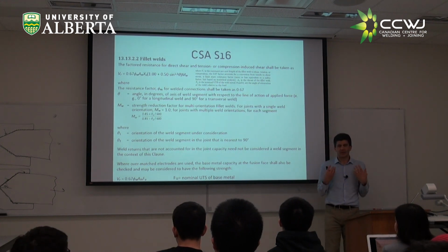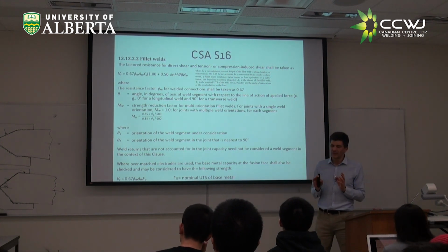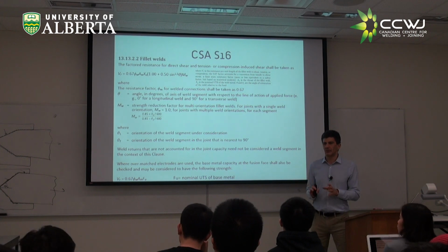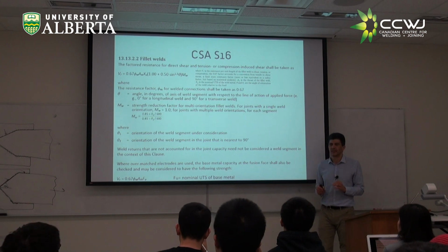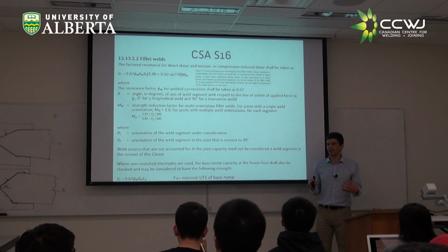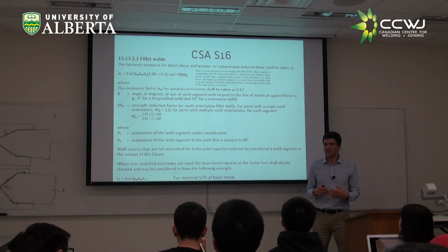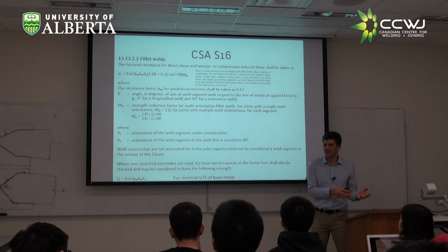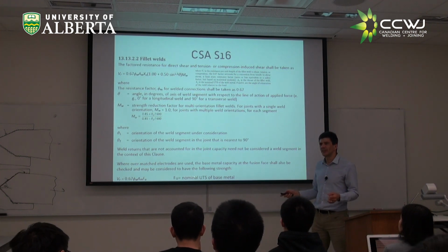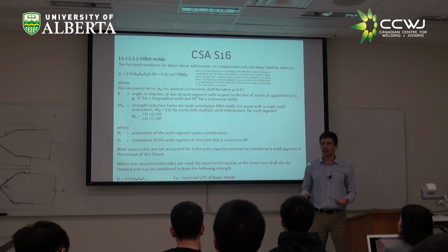Now it's funny. For example, if I have a 7018 electrode, what is the nominal UTS of 7018? 70 KSI, right? Easy peasy. But the steel, like 430W or something, has 430 megapascals yield. Okay, what is the UTS? You don't put 430 or whatever equivalent would be there. You have to go to a table.